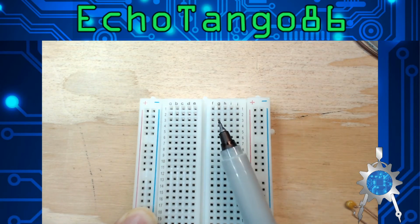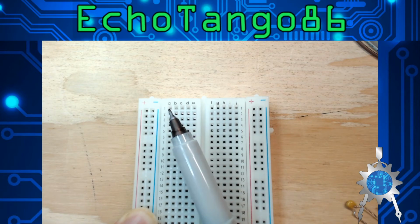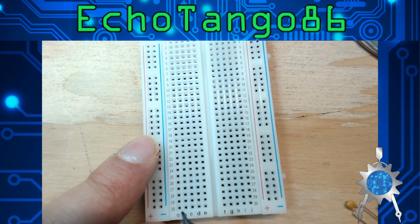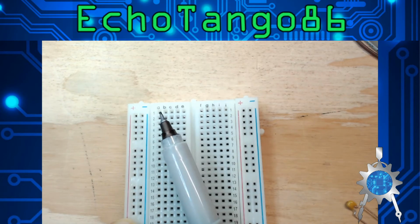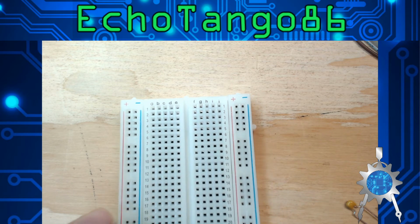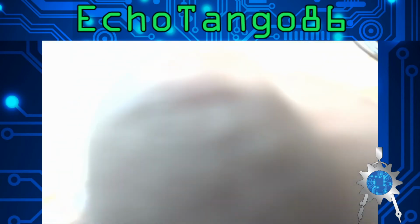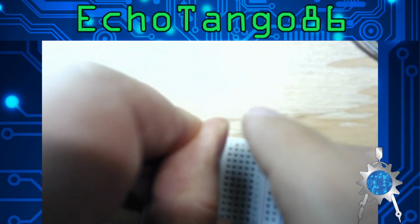On the middle part here, it's labeled A through E and F through J. And they're connected. There also are rows 1 through 30. They run this way. So these dots up along the top here are connected. The row below it is all connected this way, but it's not connected to any of them on the top. So if you plug in a capacitor or a resistor, let's show you real quick. Actually, this one will be a little easier. Let's say we put in our capacitor this way.